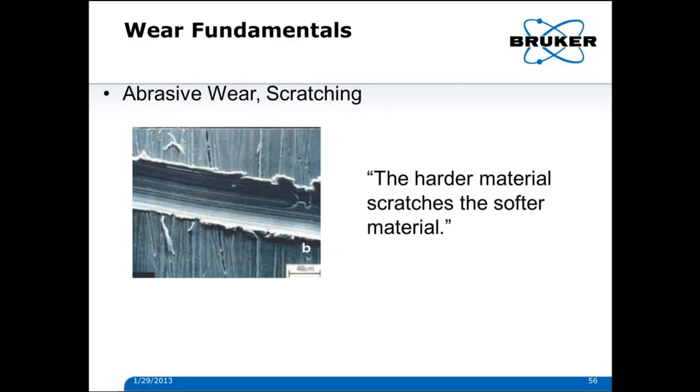Abrasive wear is known as scratching, and the key here is the harder material scratches the softer material. And the micrograph there shows one pass of an asperity, a control asperity, over the ground surface. You can see the lay of the grinding marks below it. And what you notice here is the shear lifts or the displacement. And you can imagine the next asperity that comes by off-center or next to it.